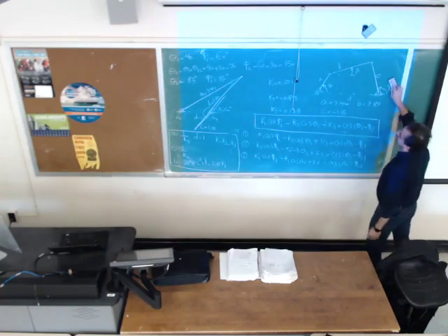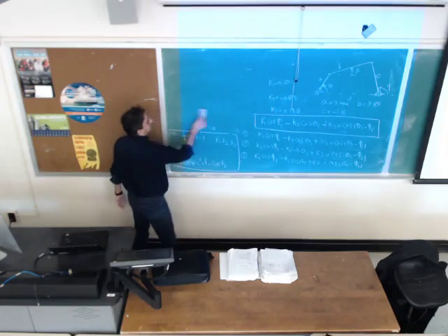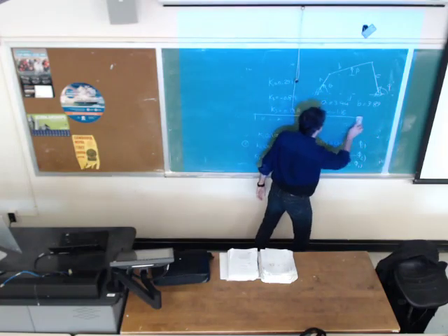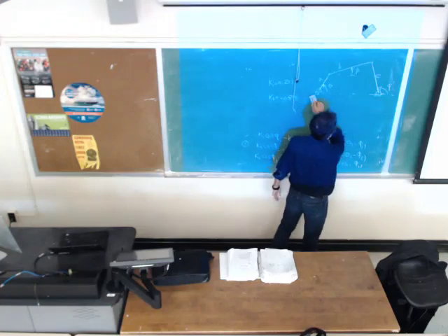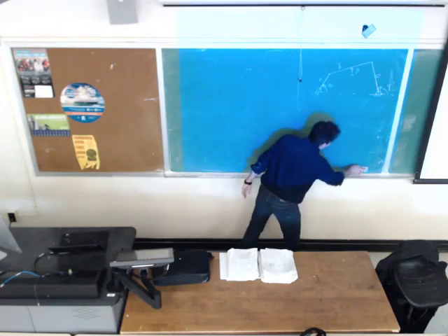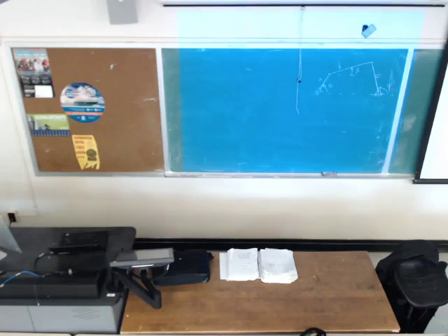All right. Let me work on one example that you are going to work on as homework. It's an important example. It's an application of the Freudenstein method. You may remember that when we started kinematic synthesis, I showed you this mechanism as an example for function generation. It's a metering device. Inside the black box, we have a 4-bar mechanism.